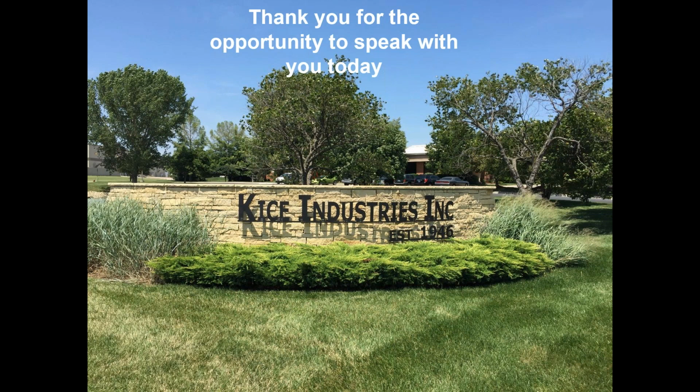Our next question, what is the typical knocking time between firing? Usually, I'm going to say 20 seconds, give or take. I think I might have been caught here. I believe our timer boards go from 0 to 30 seconds on the off time, and we're typically just a little north of 20 seconds. 20, 22 seconds is common.